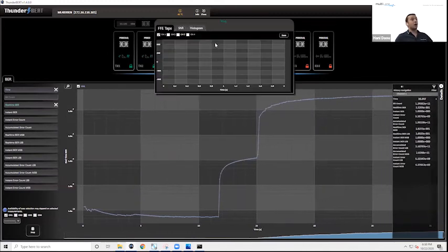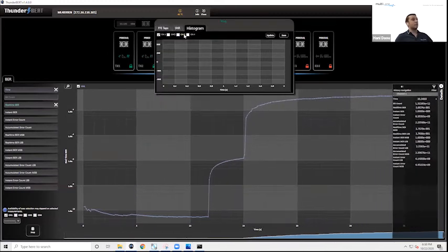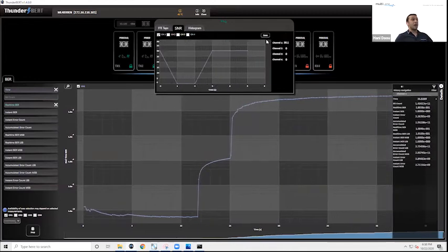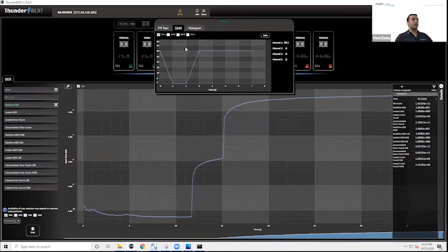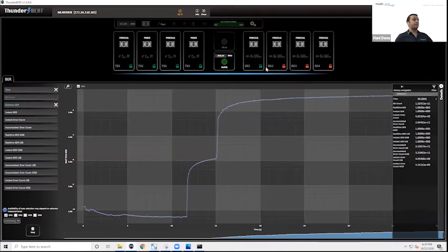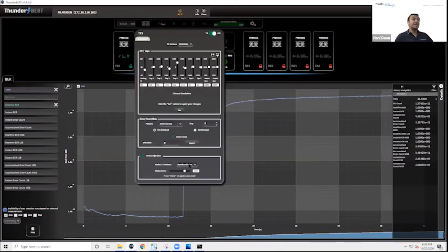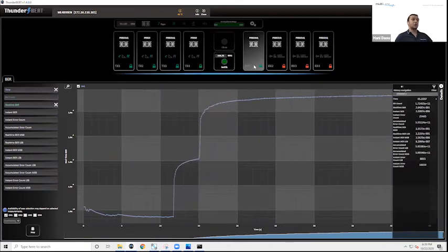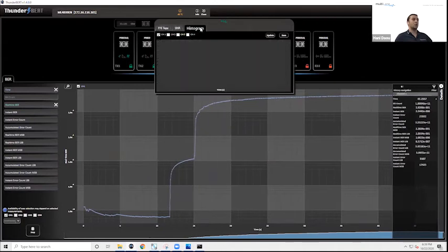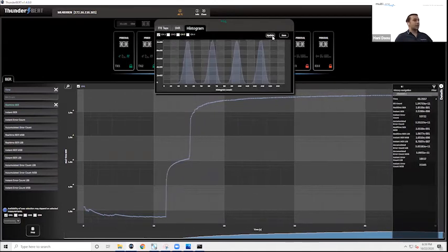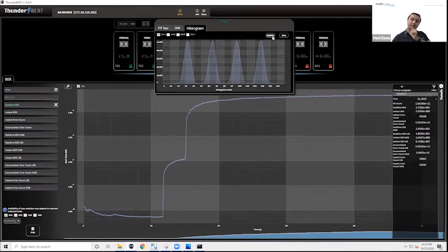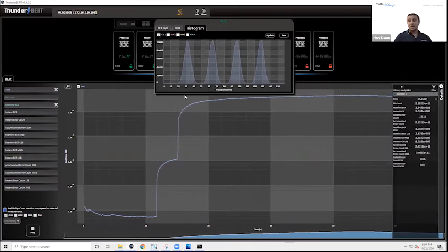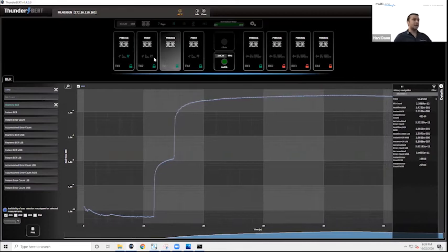I'm going to go into RX diagnostics and I'm going to look at the signal to noise ratio. And it's a mess, right? It's barely even tracking. And my histogram also is indiscernible. Let's dial the noise back a bit so we can get a lock and show you what the histogram looks like with noise. Now I will update it again. And now you see, compared to that last signal, the logic levels are a bit thicker. So that diagnostic feature really comes in handy.